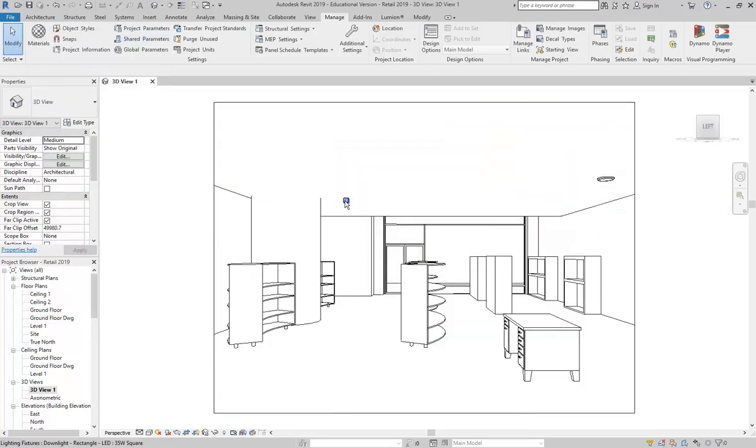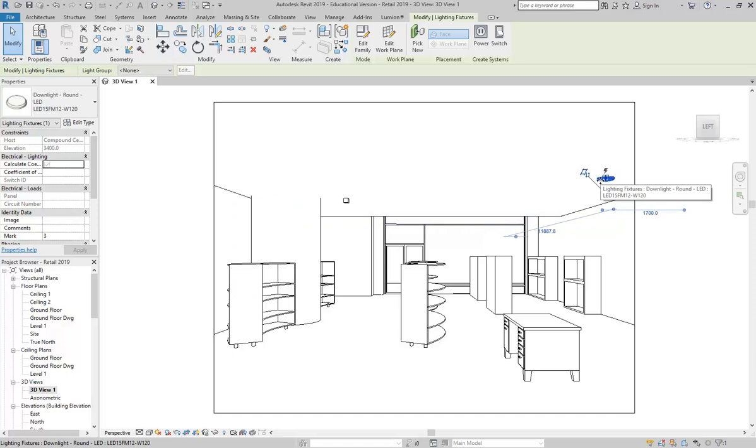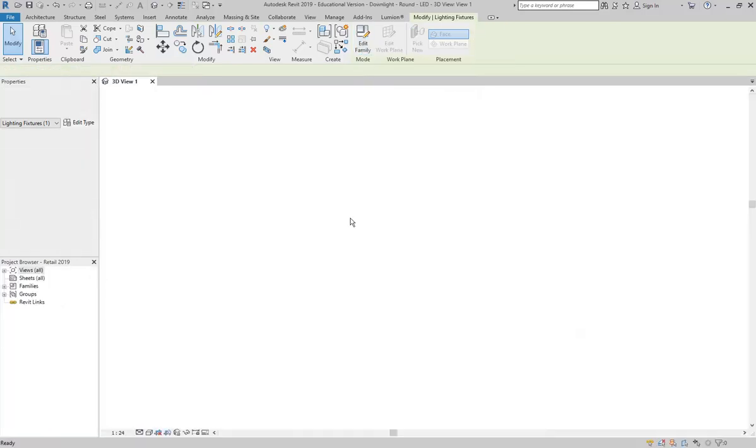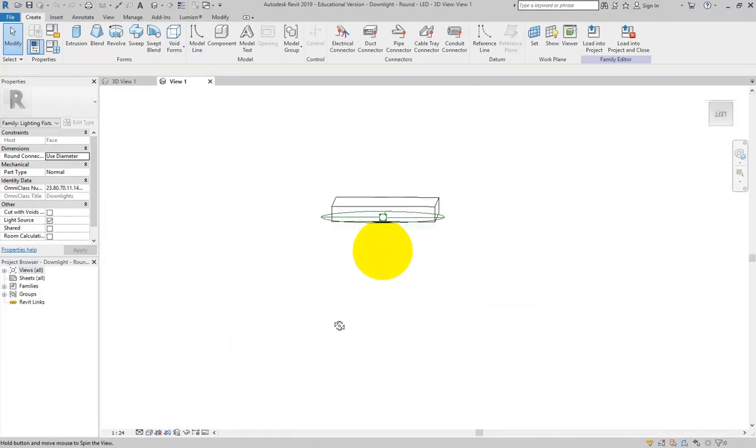And then coming back to look at the lights in Revit, now I've shown you in lighting families before how you can adjust the light emitter shape. So maybe I'll just show you. If you select a light in Revit, they're all families. So you'll always get the option to click Edit Family. And then you're going to see some of the things that are hidden in a project file.